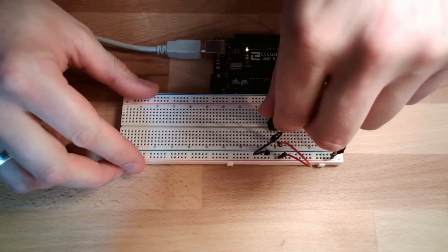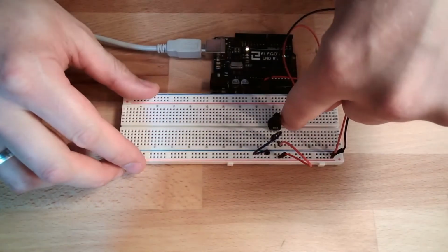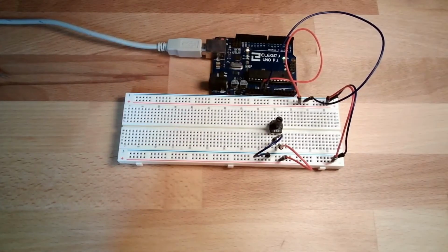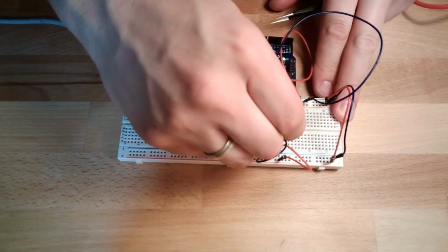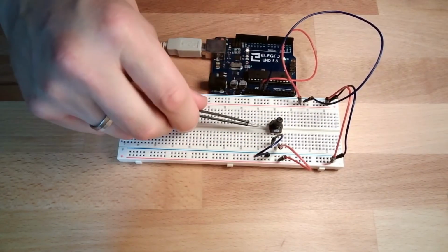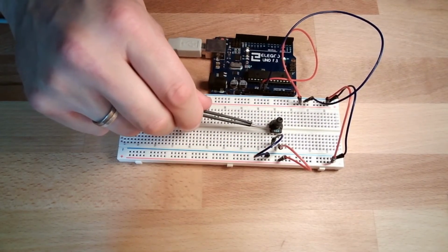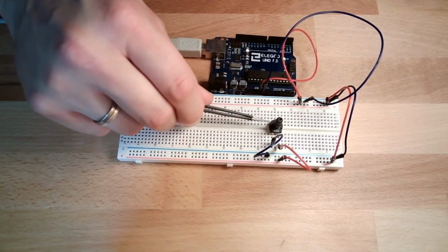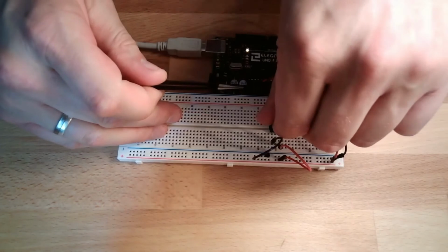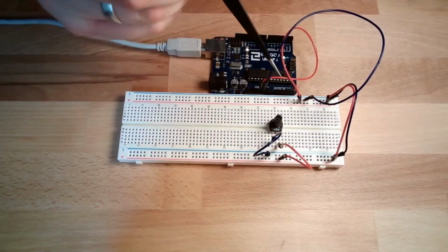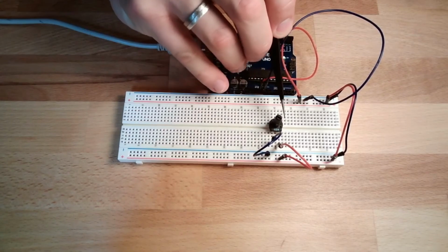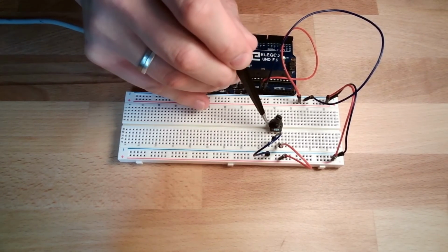We can select where we want to have the sliding contact, here on this side, or we can turn it over to this side. One time the contact is directly connected to ground, so between here and here is 0 volts. And one time the sliding contact is connected directly to plus 5 volts, so we have plus 5 volts from here to here.